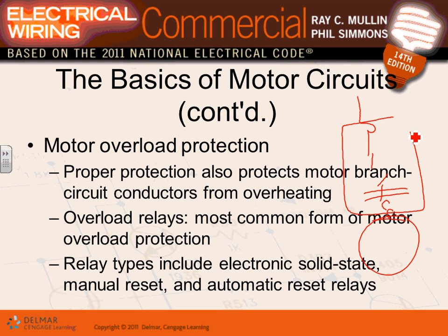Okay, the overload. We talked about overload before, and you guys sized it for us. The overload will protect your motor from being overloaded. How do you overload a motor? The motor is supposed to give you 15 horsepower. Now you're pulling 20 horsepower out of it by adding more mechanical load on the machine that this motor is driving. So you need to put in overload protection to protect that motor from overloading.